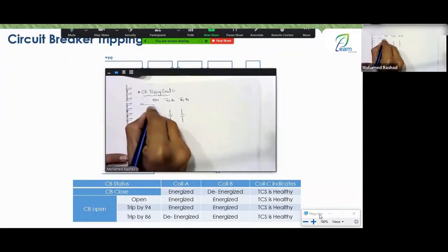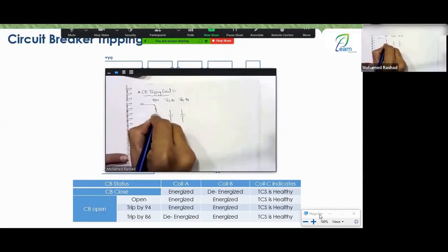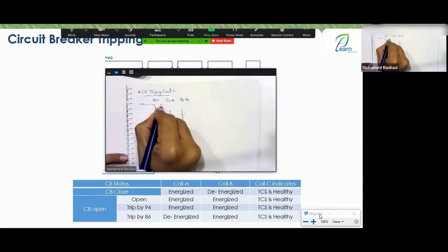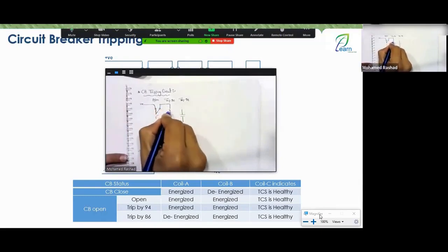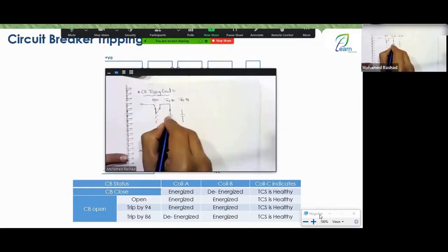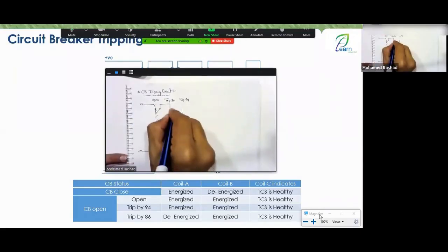Okay, let's see together. He said quite simply, we'll do it the old way. We as engineers will come here. Okay, we enter the terminal block, and from the terminal block, we enter our contact. And we exit from the head of our contact to another terminal block, and we exit from it like this, okay? We come here and enter here into a terminal block, okay? Until we go where? To the head of this contact. Exit from the head of the contact, from the contact itself, not from the terminal block. To what?